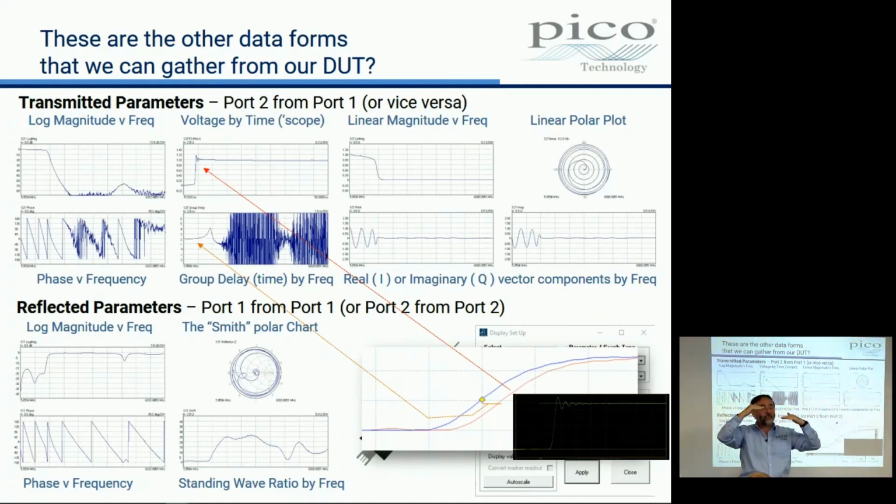Ouch, right? So it's very important in a communications channel, when you're having a modulated signal of any kind whatsoever, if different bits of the data are in different parts of the spectrum, you better have flat group delay. Because otherwise your data stream is going to get corrupted. I mean, 2 nanoseconds is huge in high-speed data, isn't it? So group delay is really, really important to communications engineers, anybody that wants to keep the signal aligned.